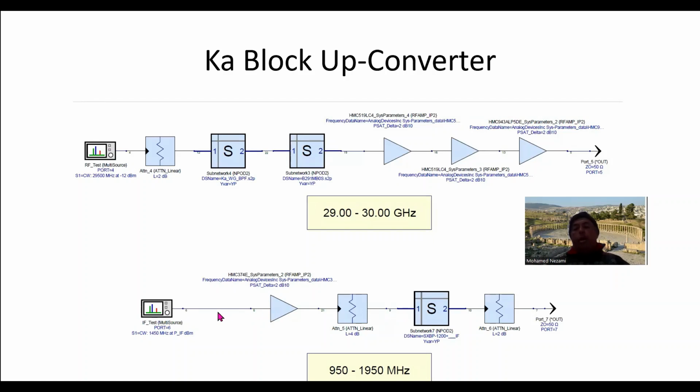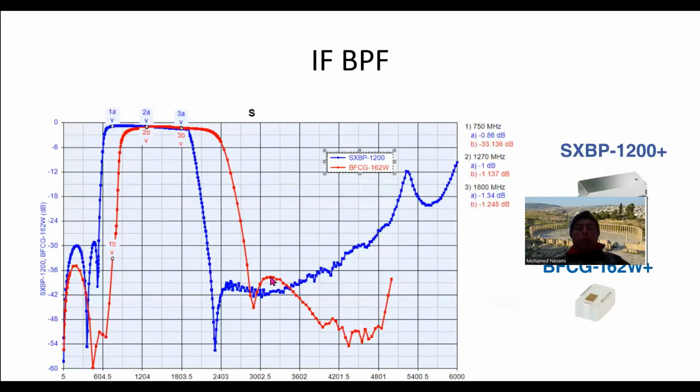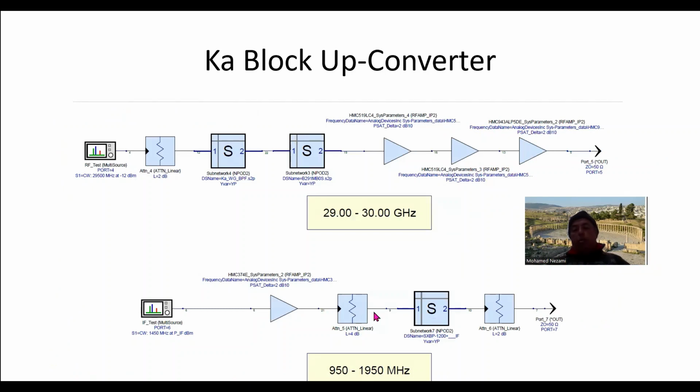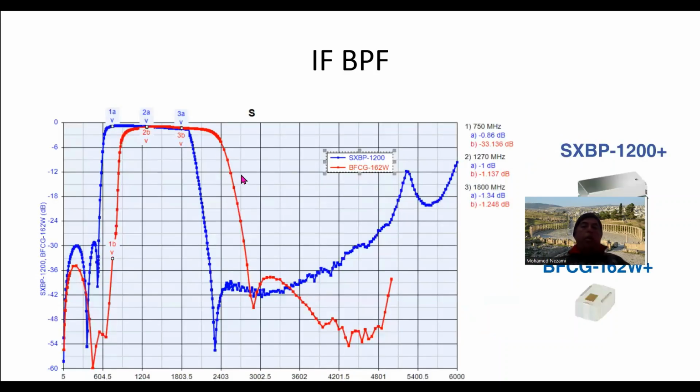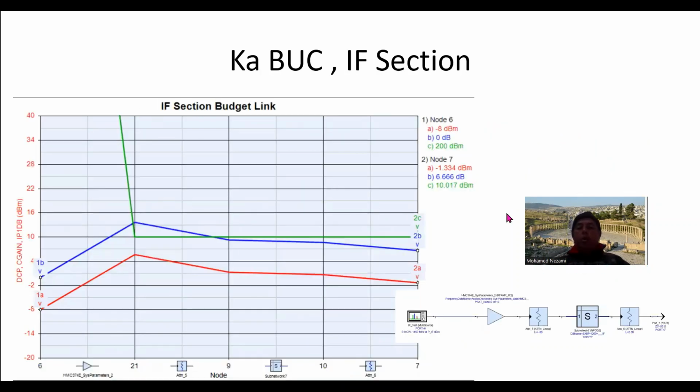So you come in from an L-band modem into an amplifier, we pad it down just to make sure that we have a good return loss. We start out with good return loss, and then we go into this filter. This filter has a very high rejection out of band. So you need to make sure that you have an absorptive piece in here. And then we pad it again before we go into the mixer. So that's the filter that we utilize, either one of those.